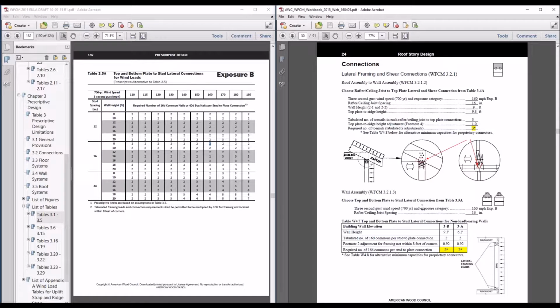The reason I only checked 16 inches on center, if you notice, we did have, I think, 12-inch on center rafters in that vaulted ceiling, but if it works for 16, it works for 12. So just note that as well. We just checked 16 knowing that 12-inch on center would work. And there are some adjustment factors. Again, check all your footnotes.